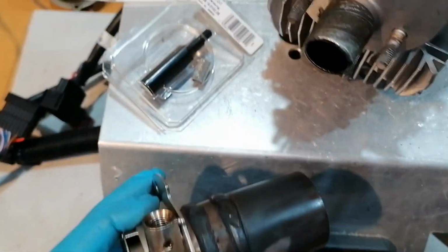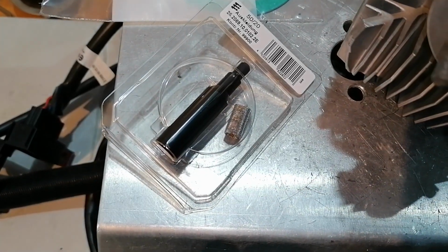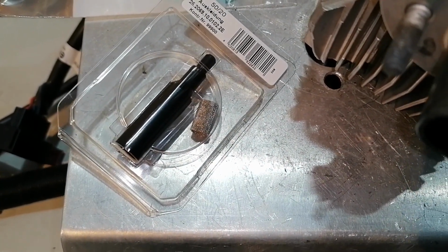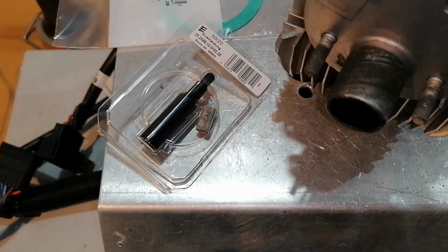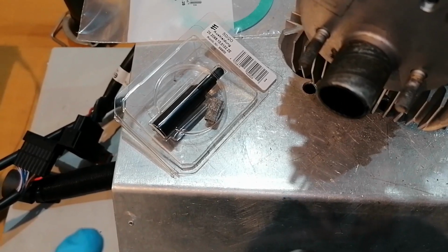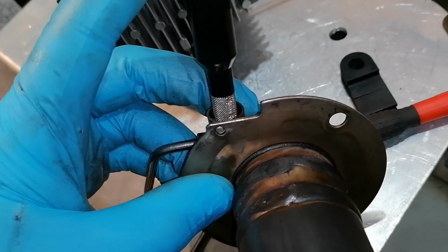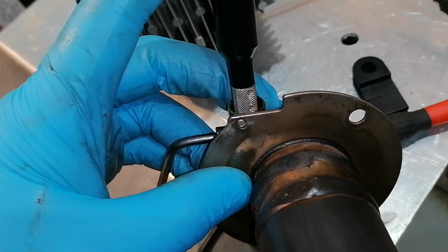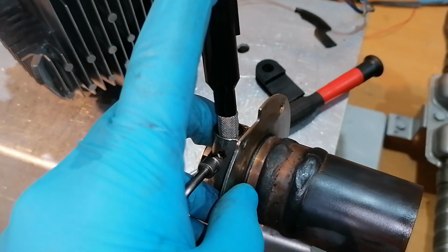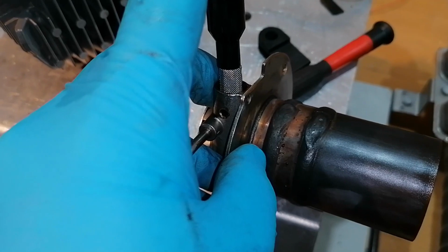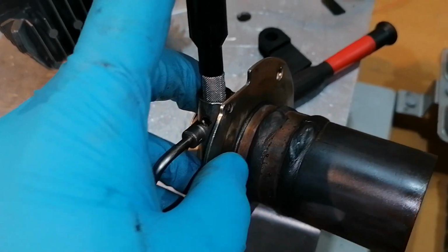So moving on, this is the spare mesh that we will put in this hole. It also has a mounting tool, so you will insert it to the required depth, so we'll be doing that. Another thing to consider, as you can see, this mesh has little spot welds, and I always make sure that I put them on the opposite side from where the fuel comes in.